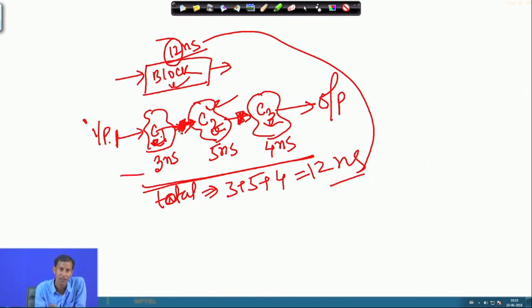But as I have put registers, how much time C1 takes to process is not at all affecting the corresponding C2. It is affecting the previously held value of C1, which is stored in this particular register. That value is now coming to C2 and changing the value of C2. Okay. So, that is why the data dependency is broken by putting this extra register in between these blocks.